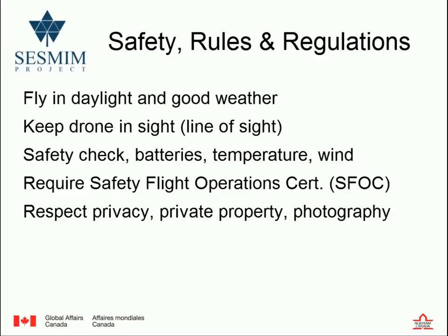Okay, so in terms of safety checking, you need to make sure that the batteries are fully charged. That's probably the most important thing before you start a mission. And in Mongolia and Canada, we have to be concerned that it can't be too cold. And in terms of wind, we probably shouldn't fly if it's above 20? If it's going to be gusting more than 20 kilometers an hour, you're taking a chance to fly. So we would recommend don't fly.